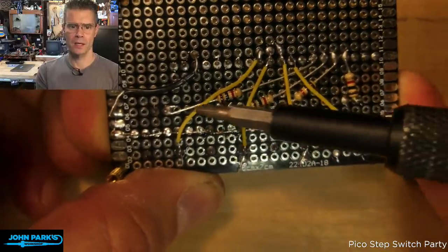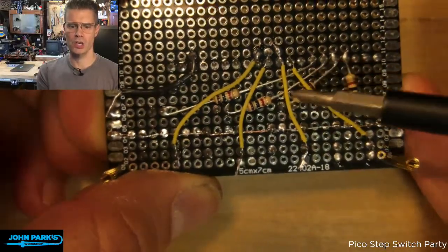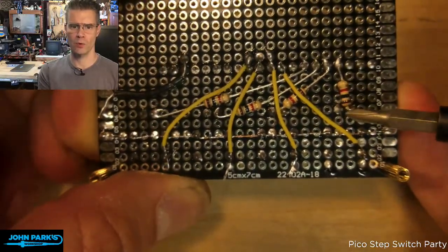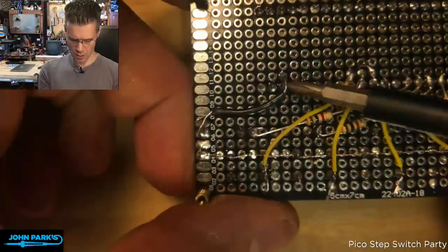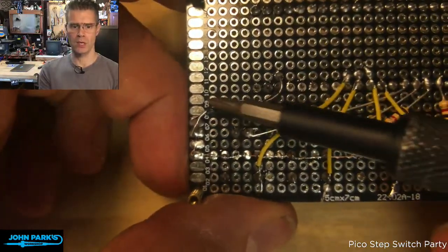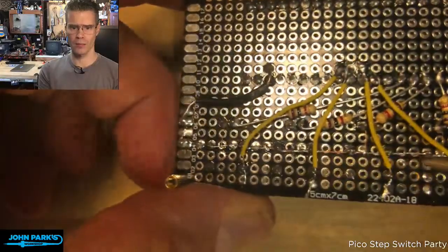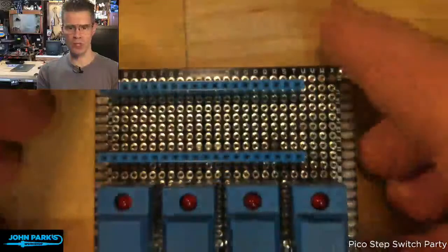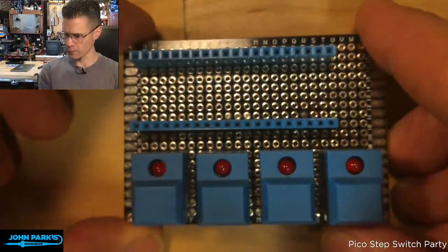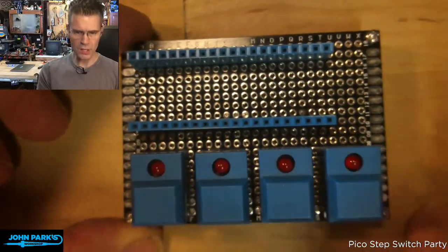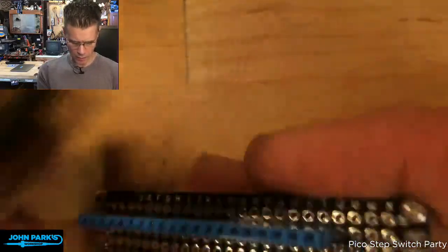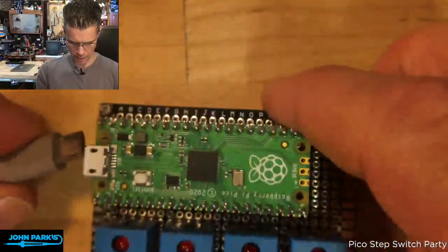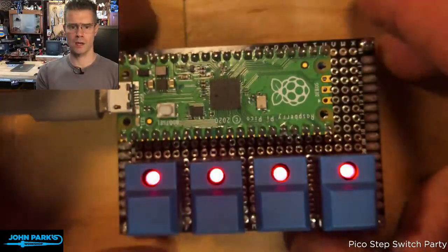And then here is each GPIO that's talking to the positive side of the LEDs going through a 1K resistor. And this up here is the ground from the Pico going to my little ground plane there. So that's the hand wiring that you'll be facing right now with these switches until we make some sort of a little carrier board. But you can see with this plugged in, we get this up and running again.